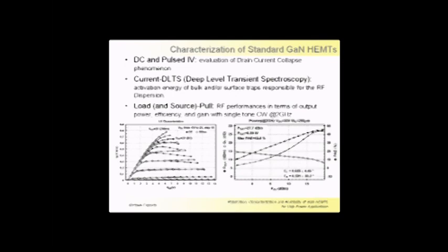This is a typical IV showing both DC and pulsed components, pulsed in a drain lag measurement setup. We can clearly see that the pulsed current level is even higher than the DC one.